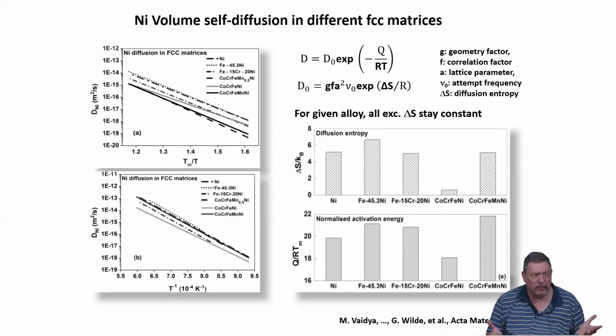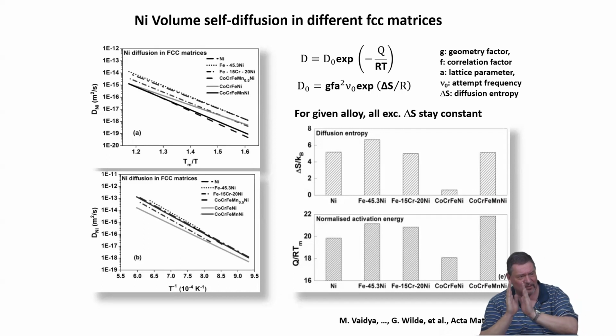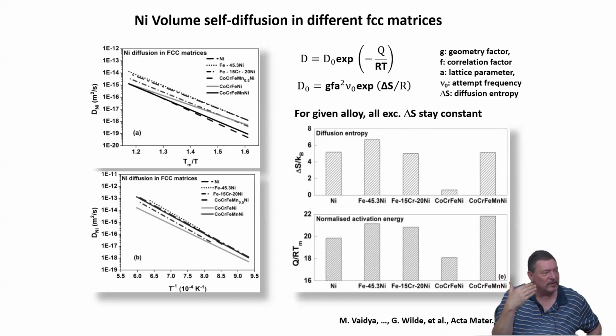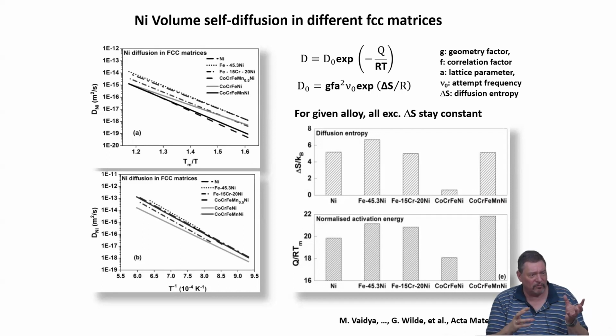And so there is no diffusion coefficient involved. It is just because of crystallography that you stabilize defect densities. And also we have this potential energy landscape, which is very complex, right? Because all the atoms are not correctly sitting on a given FCC lattice site, because you have all the interatomic interaction parameters being different from site to site. That makes glide more complex. That makes interactions more complex. This gives you a different range of how you calculate interaction products.